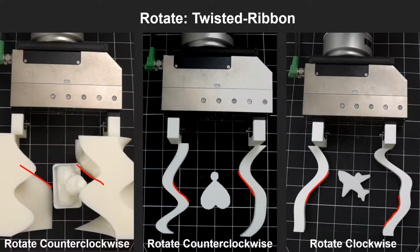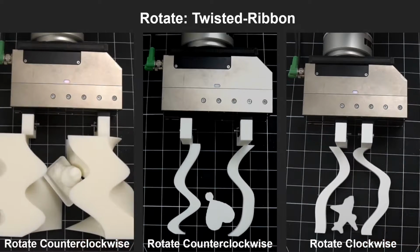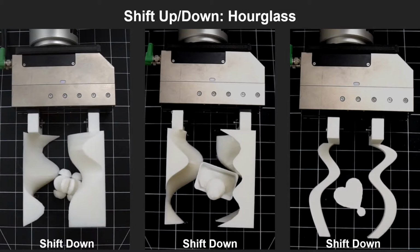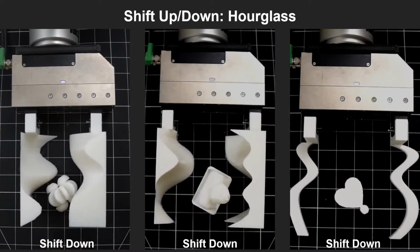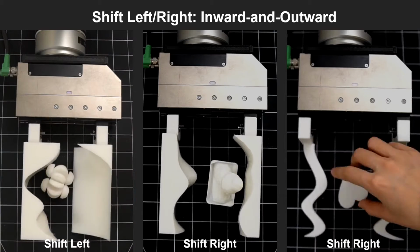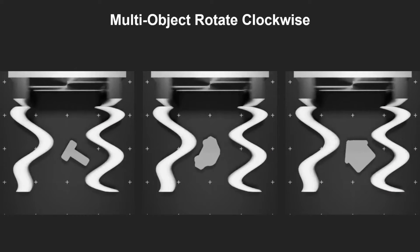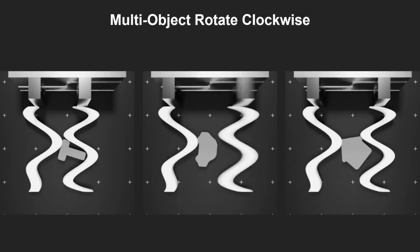The shapes designed to perform rotational movements resemble twisted ribbons, curling in a rightward or leftward spiral. For shifting up and down, the generated fingers resemble an hourglass. For shifting down, the shape presents a narrow top that gradually widens towards the base. For lateral movements, the designs exhibit an inward and outward pattern. Our framework also allows designing manipulators for a set of objects to achieve a task. Here is a generated manipulator that can rotate a set of objects clockwise.